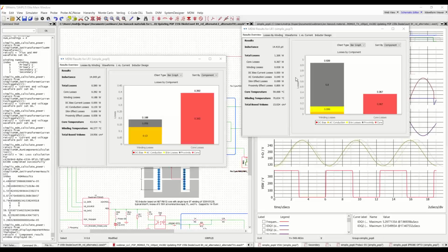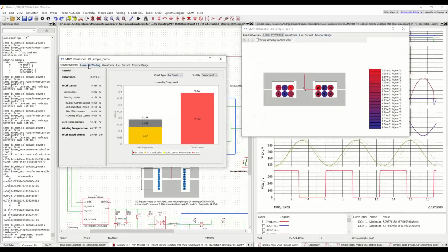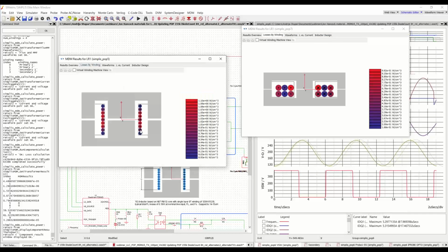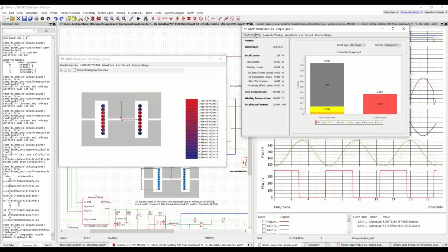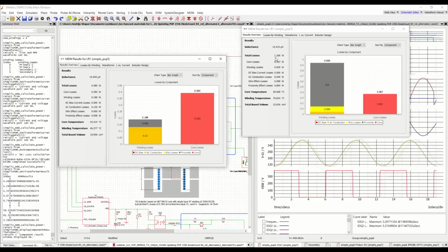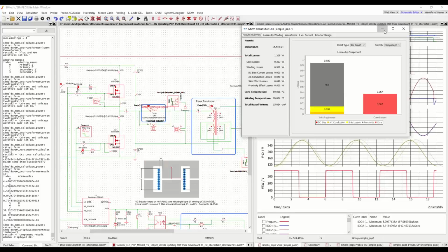But what we do have here is that it's a smaller inductor by volume, so maybe that's something you want to trade off. And it's using regular wire rather than Litz wire. So is there a cost trade-off there? That would be up to the engineer to figure out. But it seems like an amount of losses that would not be terrible to trade off for something else, especially because that efficiency curve shows that now we have more space. Let's look at the transformer.